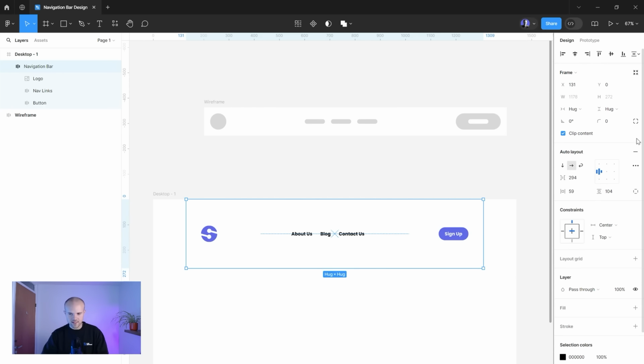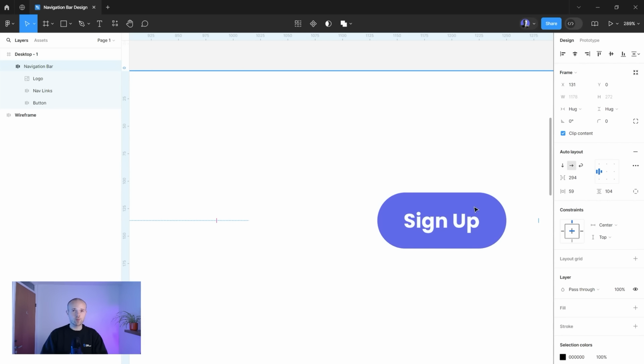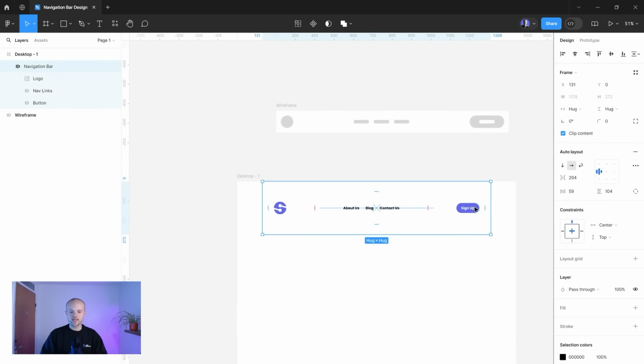And what you might have noticed happen is in the setup for your frame at the top, where we had the 1200 pixels of width before, it's now set the width to hug, just as it did with our button, which is exactly what we wanted in that context, but now we want to keep that fixed width. So where it says hug, let's change that to fixed width, and let's set it back to whatever you had before. Mine was at 1200. Height can be set to hug.